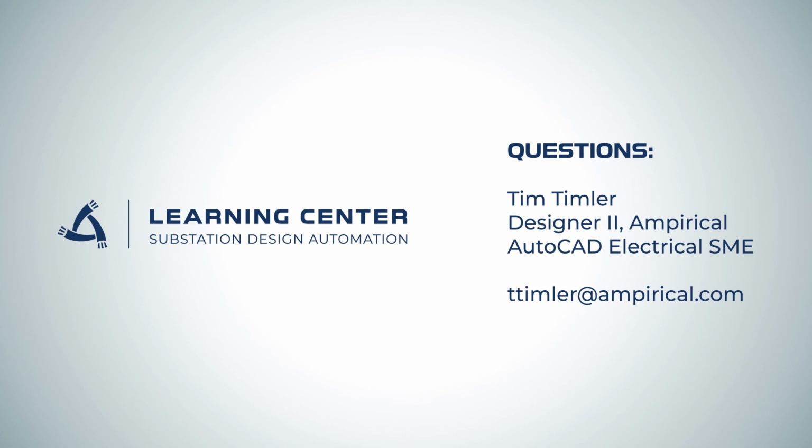The key thing to remember is that Tielinks can be customized to fit almost any application. You can add the Tielink geometry to a non-plotting layer, like the def points layer, and make them disappear entirely from the package once the drawings are printed. In next month's video, we'll explore some additional SDS Tielink functionality that will help increase the speed of your designs.